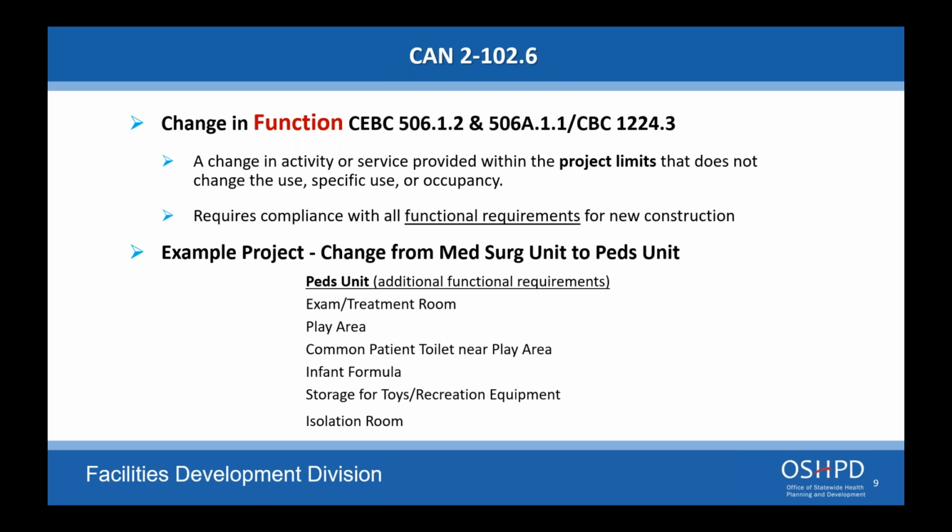What we're stating is that if you're remodeling or changing the use of a space, there are going to be requirements for fire upgrades. Fire life safety is big, and we're not going to provide a non-safe condition. The question is kind of all over the place, so I'm trying to focus in on where you're going with this. But if you're doing a change in use, the corridor may need to be upgraded depending on what that use is changing to. You can't have a non-compliant corridor system for the type of use it's going into.